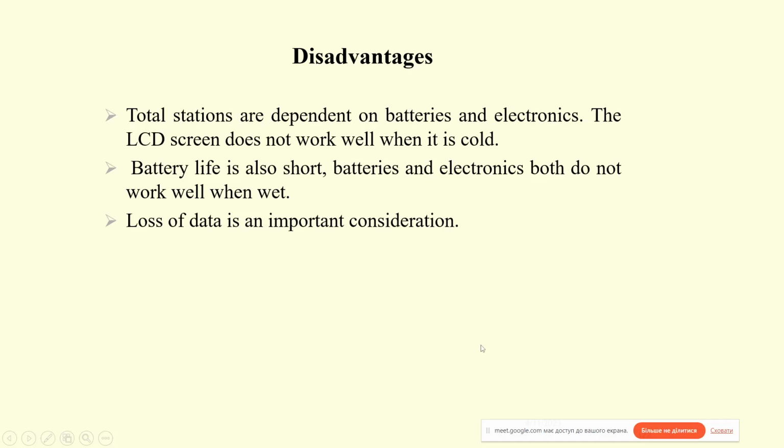Disadvantages: total stations depend on batteries and electronics. The LCD screen does not work well when it is cold. Battery life is also short. Batteries and electronics both don't work well when wet. Loss of data is an important consideration.